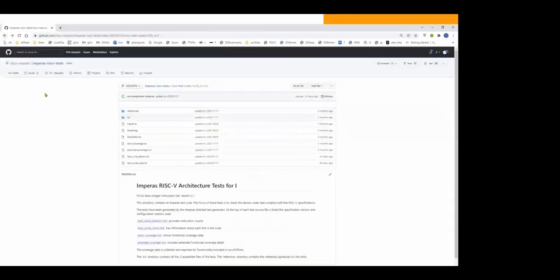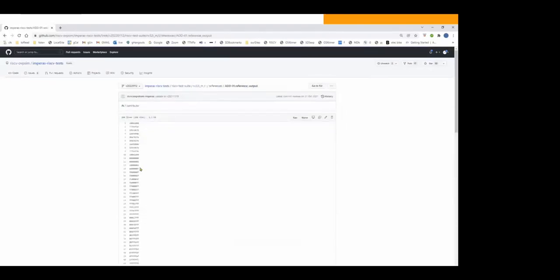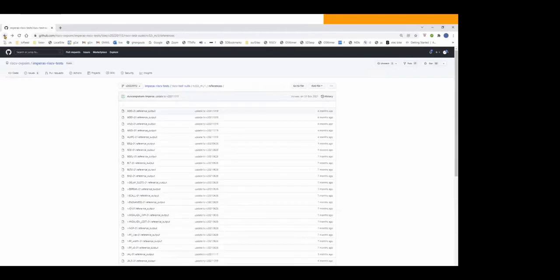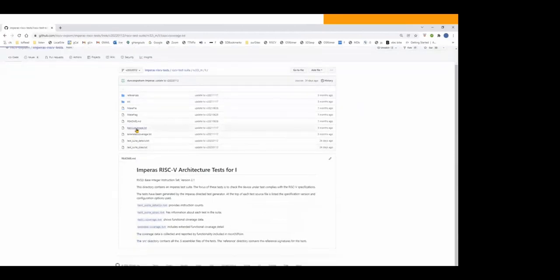And it also says what results it's expecting in there. And with the Imperas test, there are actually assertions to check the results are what we expect. We also provide references in there, so there's the signature, because it is a post-simulation signature compare methodology. And for each test, we provide several files giving you information about it.